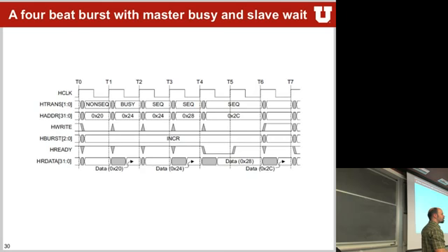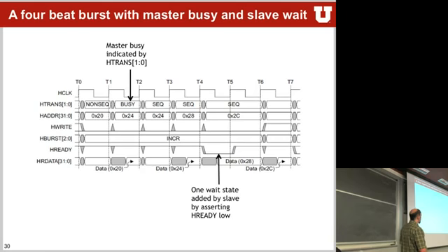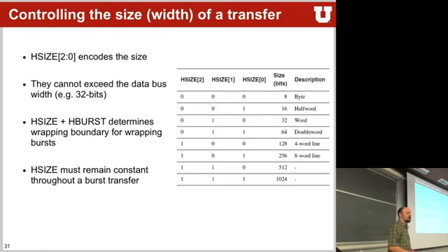It's basically the start of a burst, in this case. And then it tells it, we are busy on the transfer. So basically the incremental didn't happen, and then the increment happens in the next one. And sequence means it's in a sequence of addresses, in this particular case. And then it points to what the type of the burst is and how the sequence is set up. There are a lot of different types that can happen, so you can have different sizes of bursts and different types.